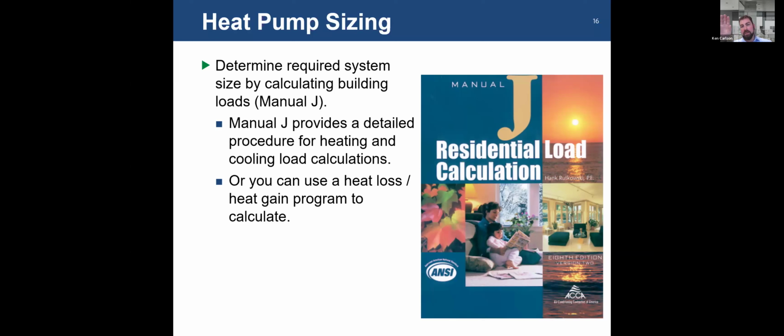And just to make a point here, I happened to be on LinkedIn a month ago when we had those cold spells. It happened to be a woman I know from work. I've gone back and forth with emails, but I didn't realize she lived in North Carolina. It was 20 or 25 degrees, and I didn't know she had a dual fuel system. She posted, dual fuel system, it's 25 degrees out, my furnace still hasn't kicked on, I'm still running on the heat pump. Even at 25 degrees, where they anticipated needing that furnace by design, I can't imagine it's much more than 20 degrees ambient. She's still running on a heat pump, maintaining the dwelling even down into the 20s with just a heat pump. So it varies, it depends.